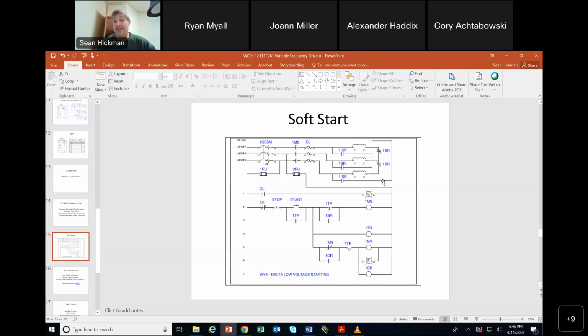It's all one unit. If you want to put in a safety relay in here, we already went over safety relays. The safety relay here would bring down my motor starter so that we would open these contacts. So there'd be a set of safety relay contacts right here, and then a whole separate safety relay that had its own wiring, the purpose of which is to open up the contacts here. You don't need that. We're not doing it, but our guard logic safety relays have dual channel contacts, so if we wanted to incorporate the safety function, the dual channel safety is already in there, and it can shut itself down with a dual channel e-stop. It's got its own safety relay built into it. So yeah, it's safer because we could wire this up and add a safety relay to it. But this is starting to get pretty expensive with all these parts, probably more expensive than a VFD.